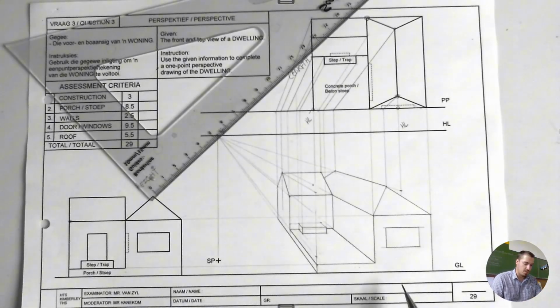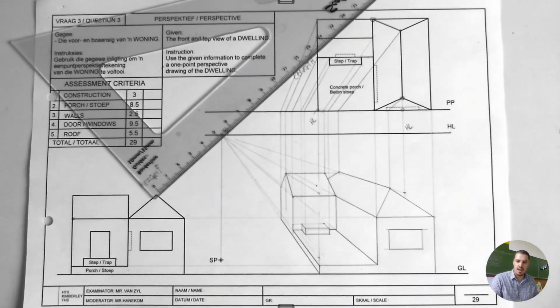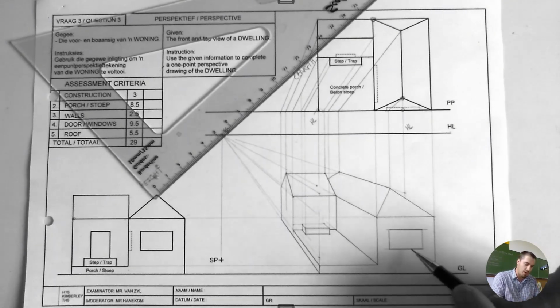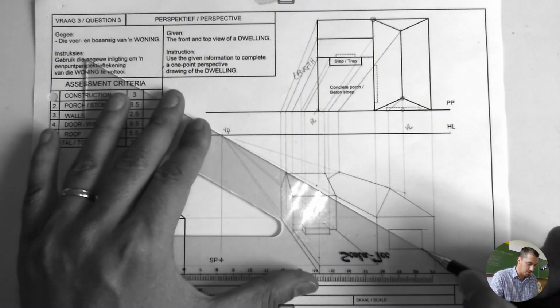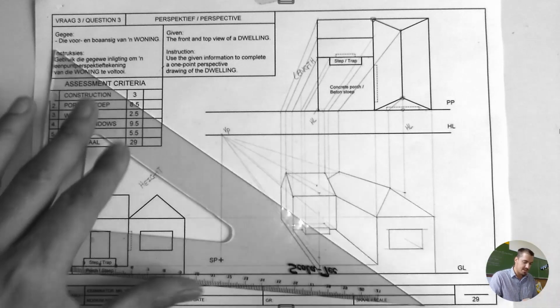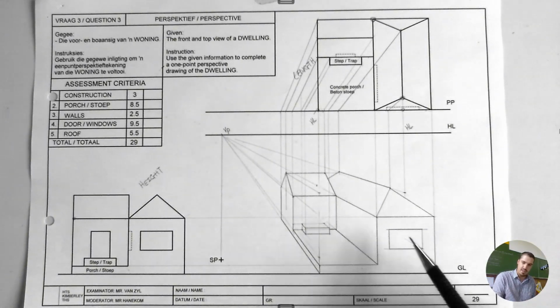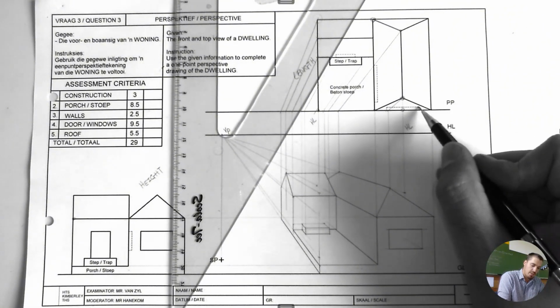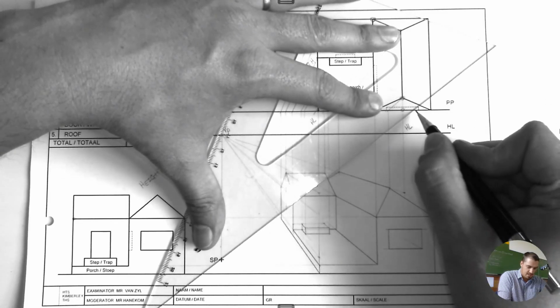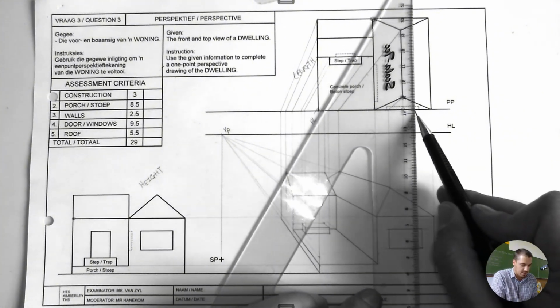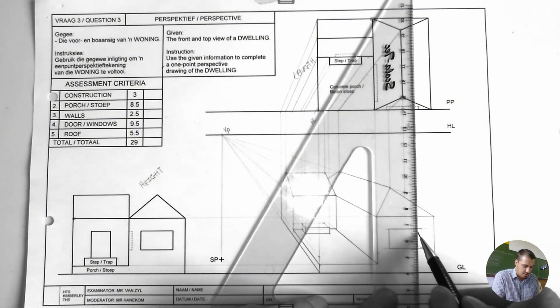Right, there's the window. But now obviously this window is also going to have depth to it. You are going to see the frame or the sill, which means you're taking this point to the VP and you're just extending a bit of a line. Obviously it's not going to be that big of a distance. So I now need to determine this width, the length. So I'm going to take this inside point, SP, and you can see it's not that big of a distance that it makes. It only goes up to there. So that is going to give you the inside frame.